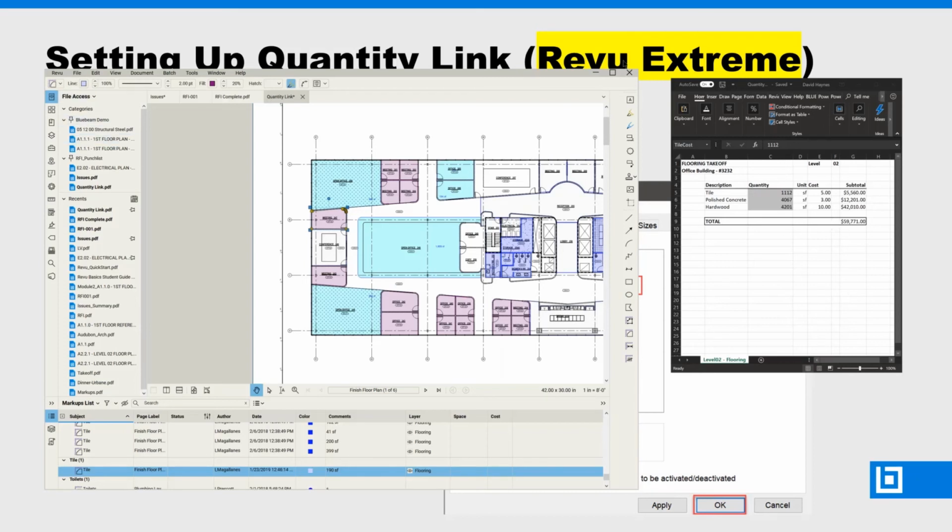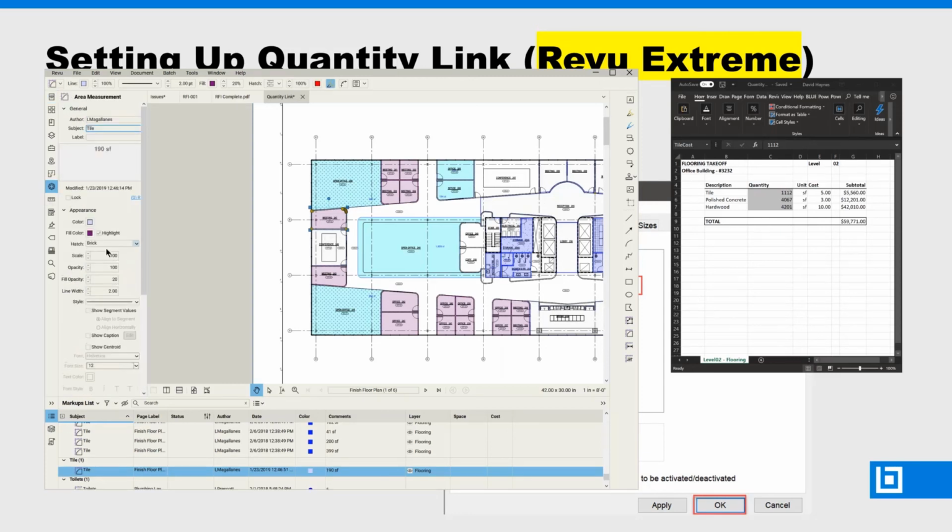So as I make changes here, I can have them show up on the other end. That's the problem with the split screen, I can't quite see correctly. Any changes can be made. I think maybe the problem I've made here is I didn't do it up here in the properties. As long as I have them be the same, I can modify finishes, I can add finishes, I can delete finishes in that way.